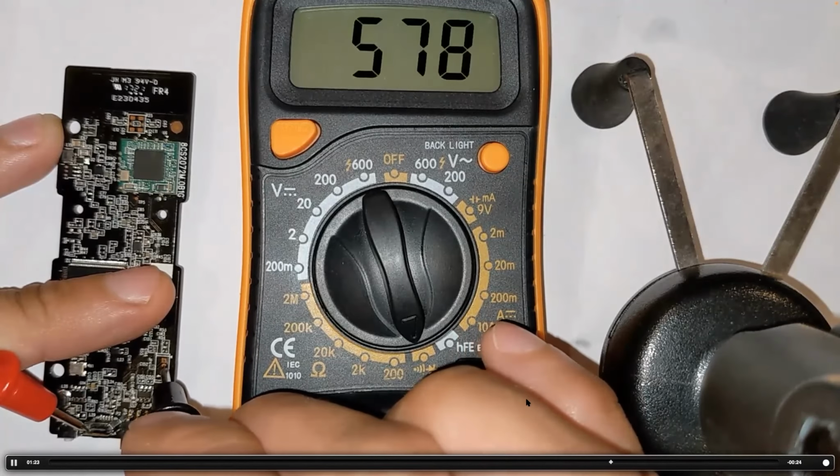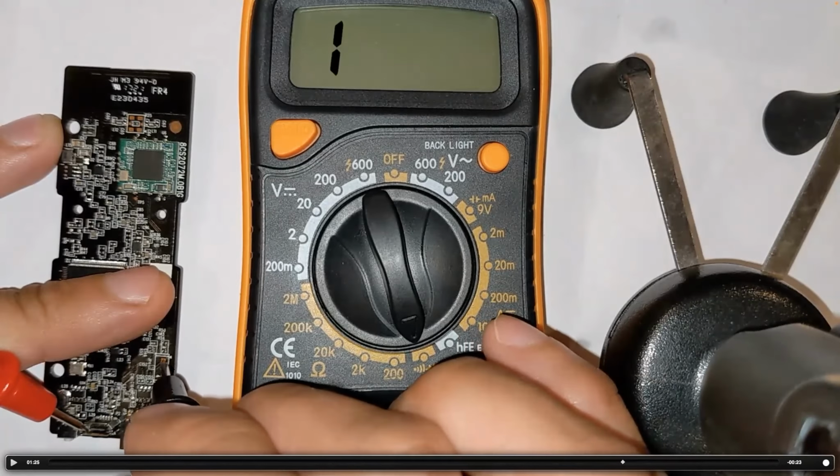So let's say this particular pin is ground. As soon as we put the black probe over here and the red probe is already in a common reference ground, the internal circuitry of the multimeter completes, and there's a small buzzer inside it. So you'll hear a sound whenever the circuit is complete, and that's how you'll know that this is the ground chip or ground pin.